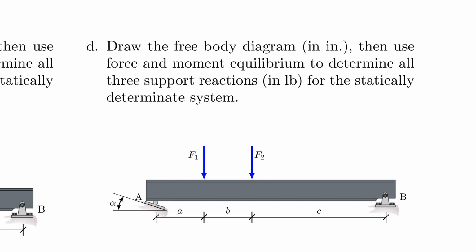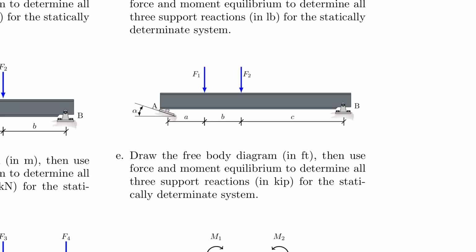But you can use your moment equilibrium to find the support reaction on both sides. And then please understand that you can always break this down into components that are vertical and horizontal, and together they might make the perpendicular component. But maybe I gave too much away now. But anyways, you can solve this problem. Just pay close attention to the surface and what that means to the support reaction. But if you really think about it, I think you will have no problem solving that.